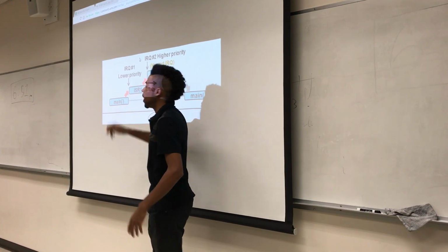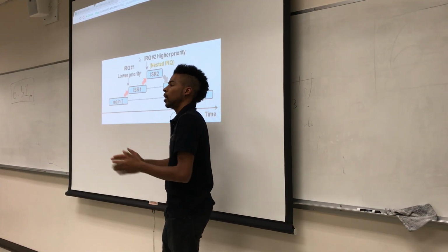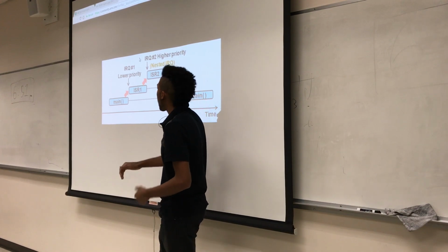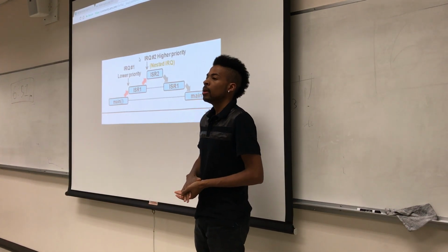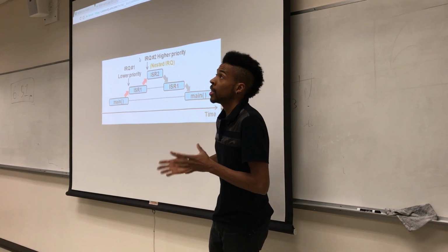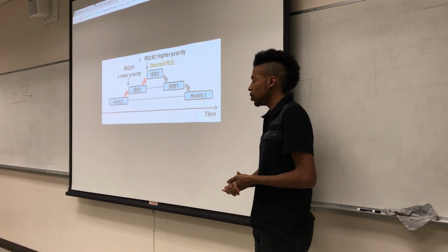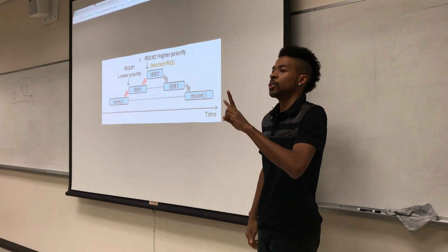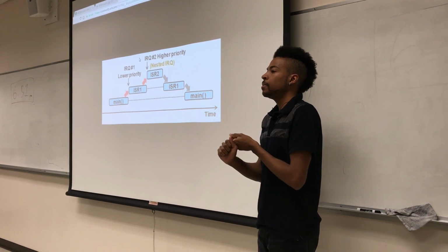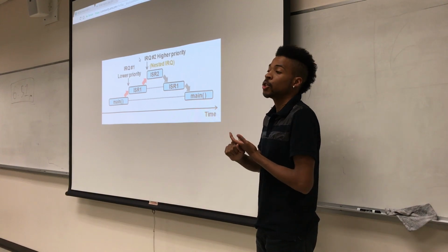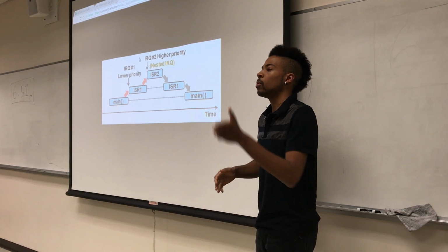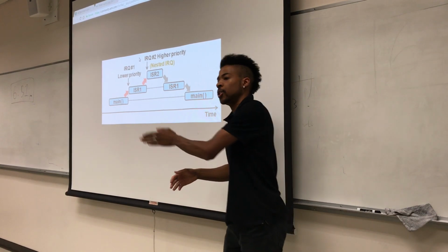It'll jump into, let's say, ISR1, run its service routine, but sometime in the middle of that, it might end up jumping into another interrupt that has a higher priority. So nested interrupt systems, interrupt controllers, typically have two things: priority and the ability to nest. So you can have multiple ISRs running within each other.